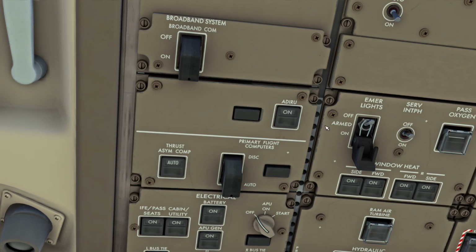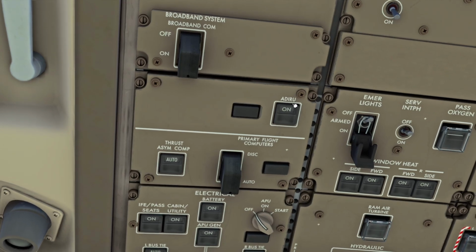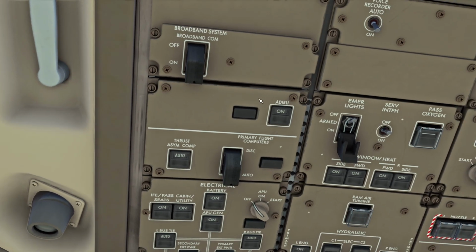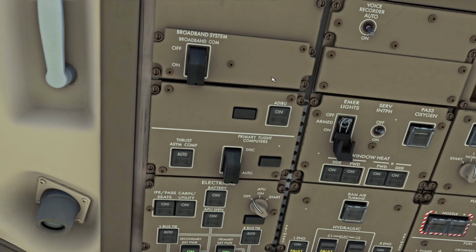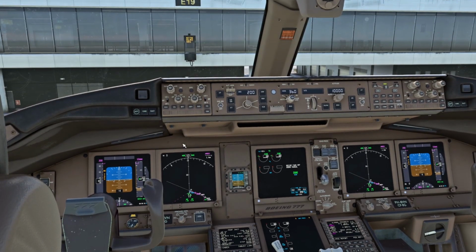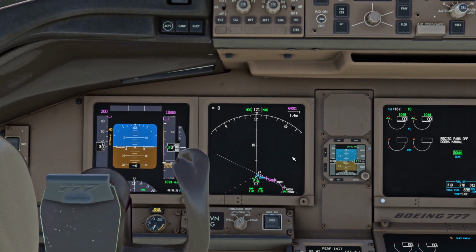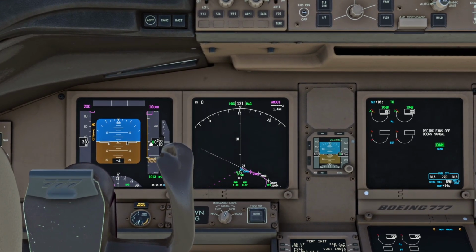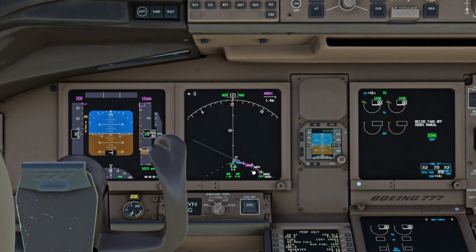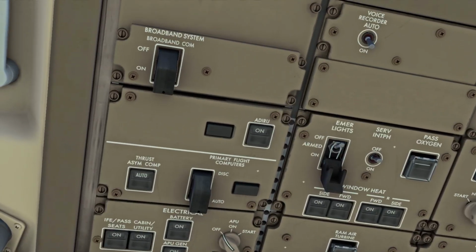Make sure it's on, that the off light is extinguished, and that the on battery light is extinguished. And yeah, like I said, it will align the aircraft's position to true north, provide attitude information and other information to various systems on board the airplane. As you can see, in the meantime, it is already aligned, showing the displays and the attitudes on the PFD, and allowing us to check our navigation display. So that is all in order.